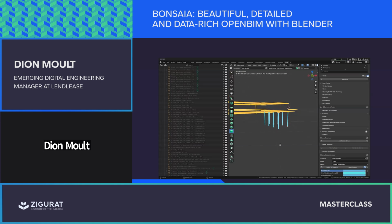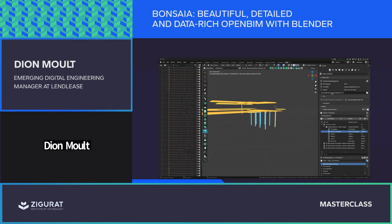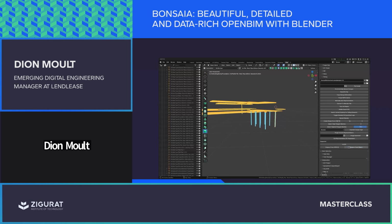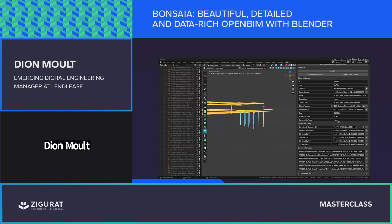So now they have a different color. And then I guess for the really technical people in the audience, we can actually inspect to see what's inside the IFC definition itself. So if I go into the quality and coordination tab, I can actually pull this up and say, all right, you are a pile, and here's your actual definition in the IFC database. So you have these types of relationships with other objects.